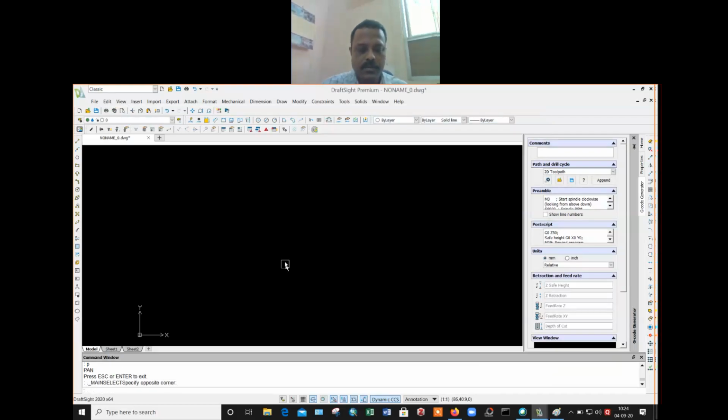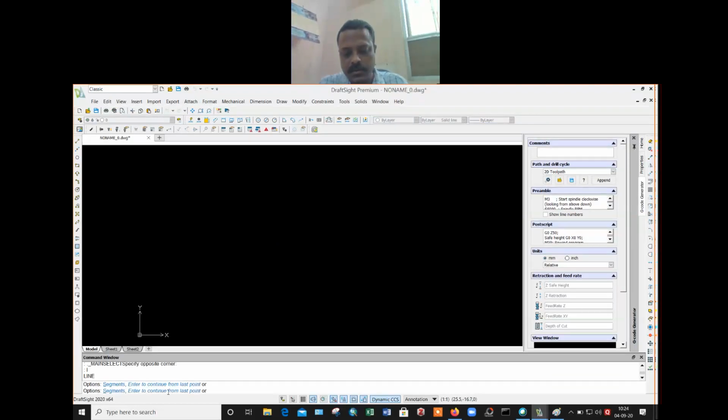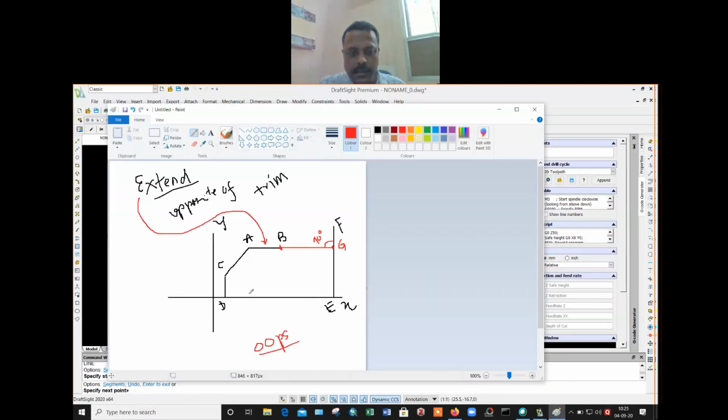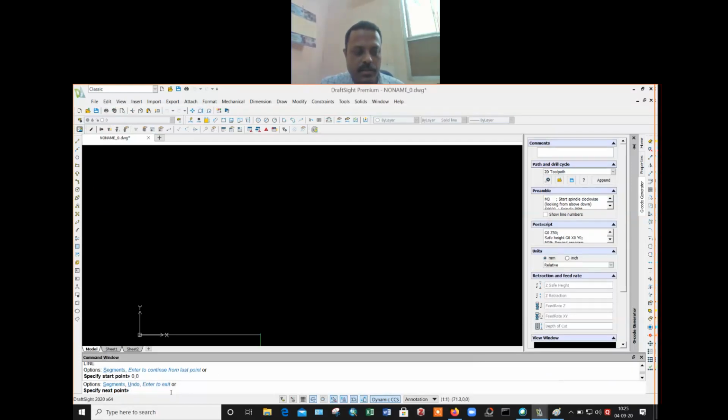I draw a line starting from 0,0, and up to here it is maybe 100 millimeter in x direction. So I say @100<0.